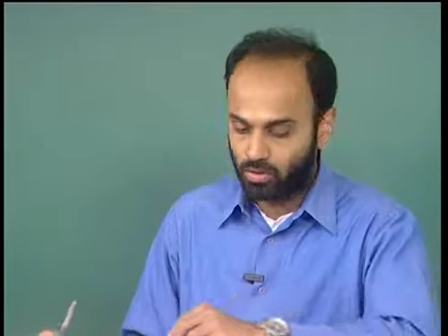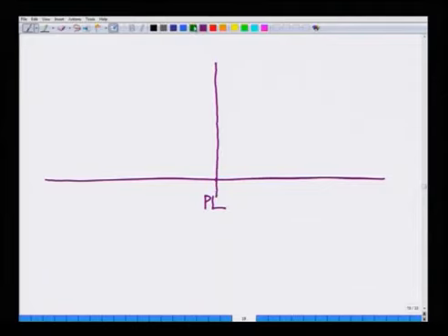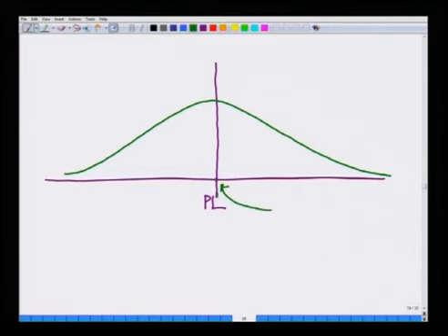What we are saying is as follows: if I look at my path loss, my median path loss or my mean path loss is something that looks like this, and then I have a random variation about this mean. So, this is the median path loss, and then there is a deviation about this with a spread. This is the spread, which is nothing but sigma.